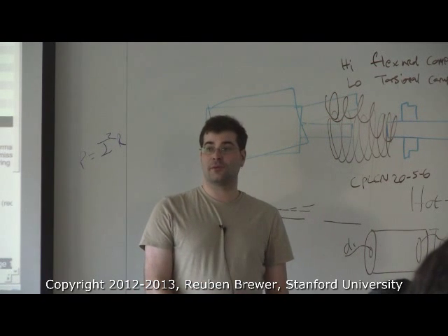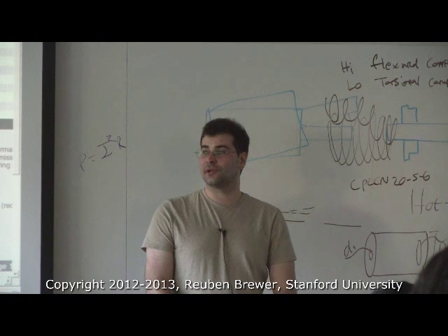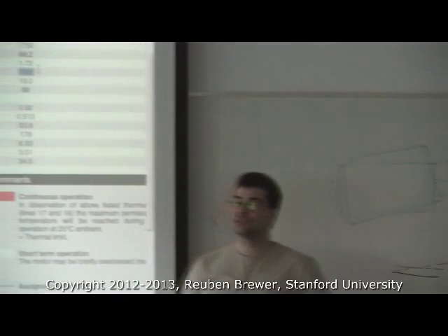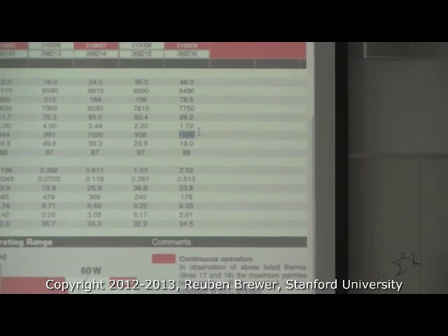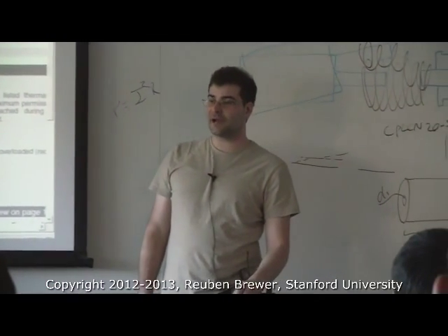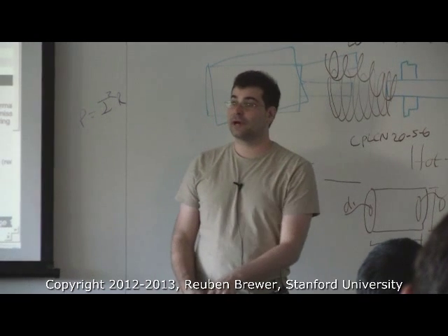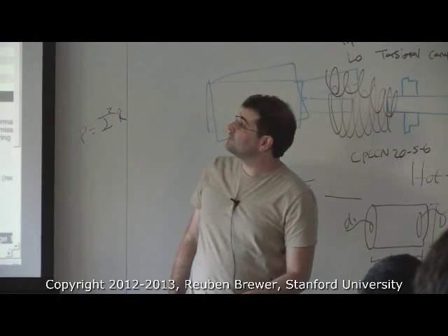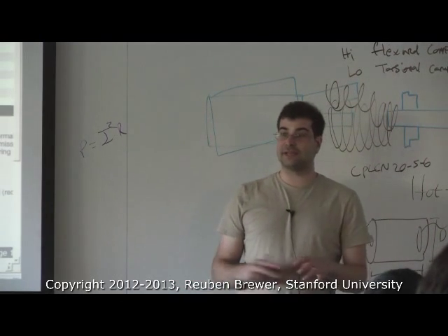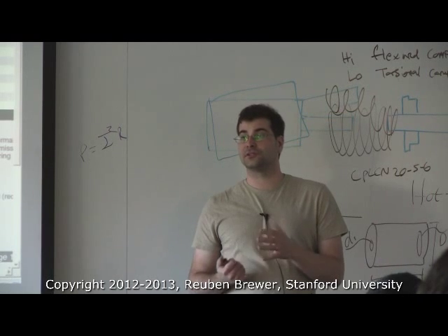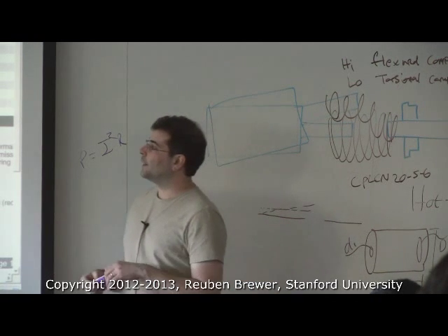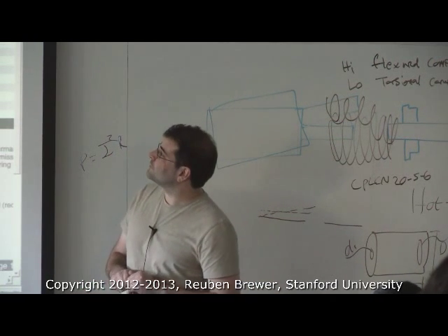Now, what would happen if you were Lewis Whitcomb and you were doing underwater robotics? Would these max continuous currents be the same, if you had a motor undersea with a giant heat sink of water? No. Keep in mind, there are some special cases, such as underwater robotics, where you can drive much nearer to stall torque because, compared to the size of your motor, you have the infinite heat sink of the ocean to cool you off. And you can play tricks with fast convective cooling, but most people in research aren't going to do that.